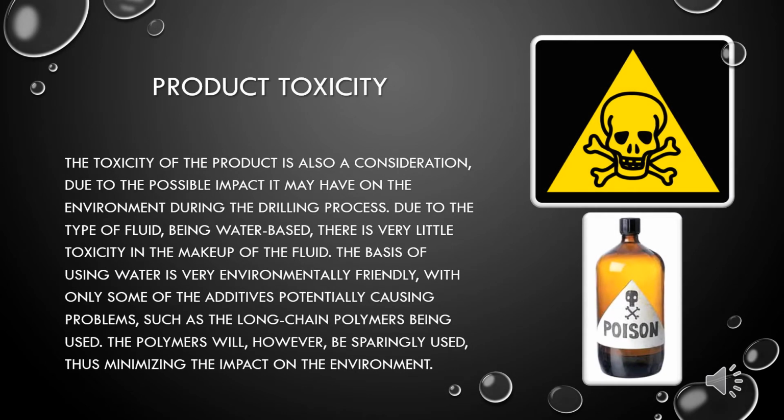Product toxicity. The toxicity of the product is also a consideration. This is due to the possible impact it may have on the environment during the drilling process. Due to the type of fluid, being water-based, there is very little toxicity in the makeup of the fluid. The basis of using water is very environmentally friendly, with only some of the additives potentially causing problems, such as the long chain polymers being used. The polymers will, however, be sparingly used, thus minimizing the impact on the environment.